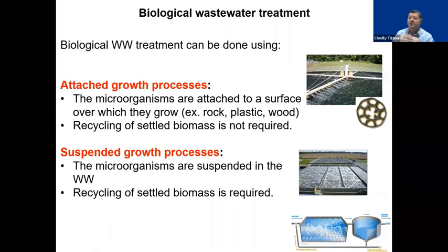You need a support material, and on that support material you will form biofilms of the microorganisms where they grow and proliferate when they are in contact with the wastewater, and they use the materials that are in the wastewater to grow. That's the attached growth. The other type of process which is widely used is the suspended growth process.